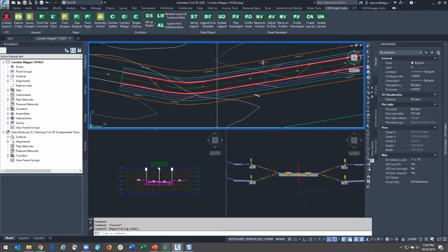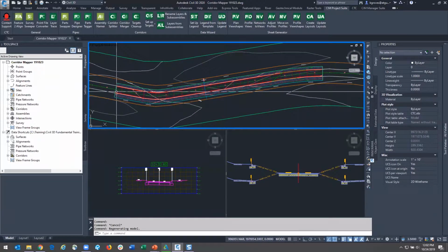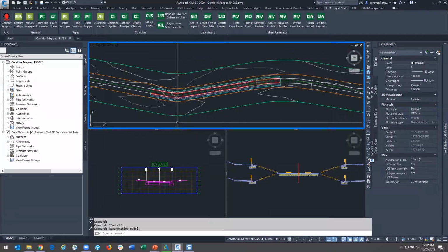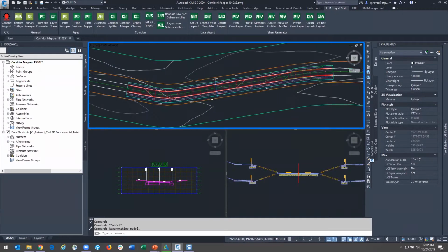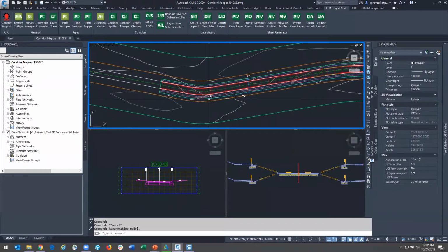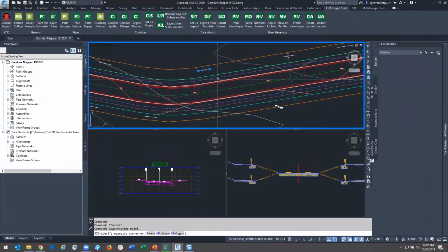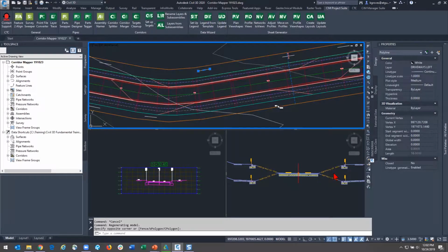One of the use cases that I'll be showing today is what I would call a simple corridor design. Now that doesn't mean that we don't have targeting or whatever else, but we're not including an intersection. We're just going to be doing a nice long single roadway, or a single corridor model with that one roadway in it. But what is not so simple and what can be very frustrating is using conditional subassemblies for a target found, target not found workflow.